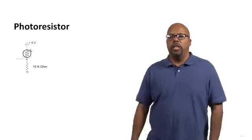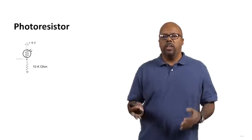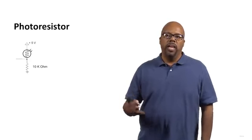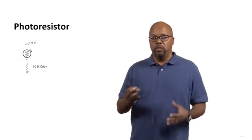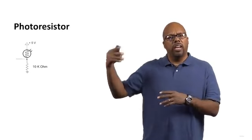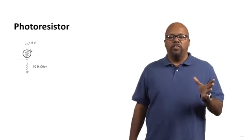So here's an example. You might have a photoresistor. So you can see that's a voltage divider. The bottom resistor I've made 10 kilo ohms, and the top resistor I have made a photoresistor. That's the symbol for a photoresistor. It's basically a resistor with a circle around it, some arrows coming in because it's detecting light. And so it's a voltage divider.